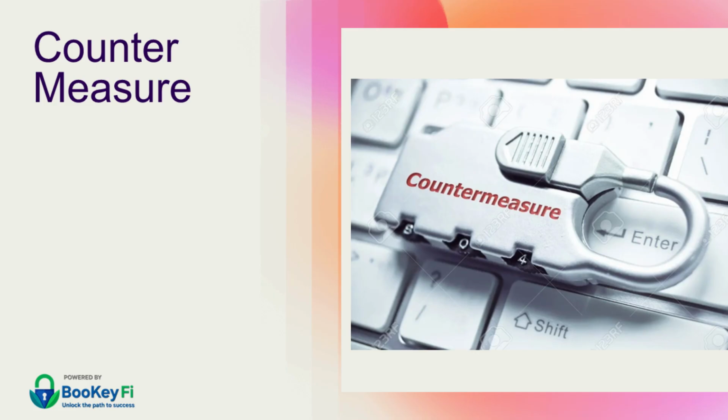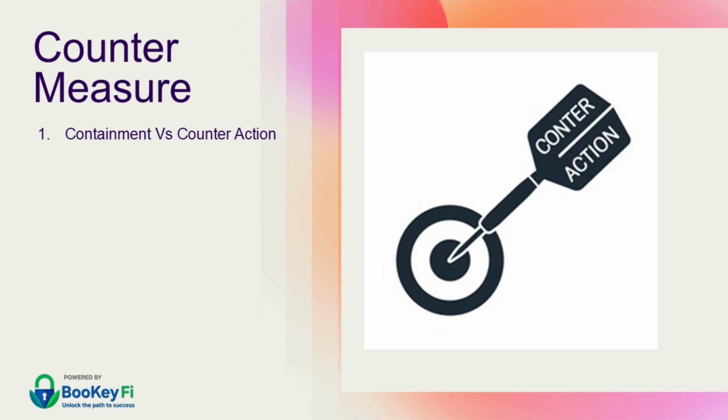Countermeasure. This is the only permanent fix. A true countermeasure is a process change, not just a "be more careful" reminder. We must do both countermeasure and containment. Containment is a short-term solution, like wiping up a leak. But a countermeasure is a long-term remedy, like replacing the seal with a high-heat version.